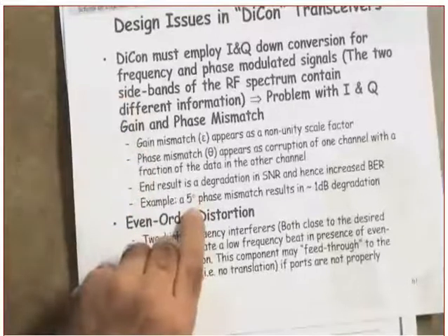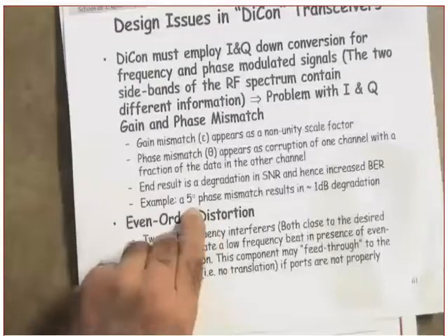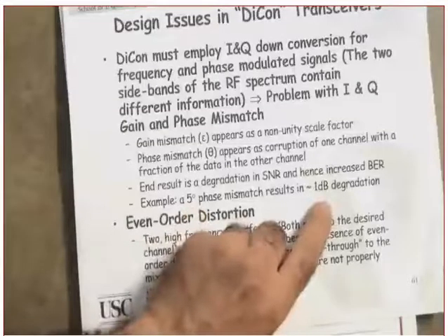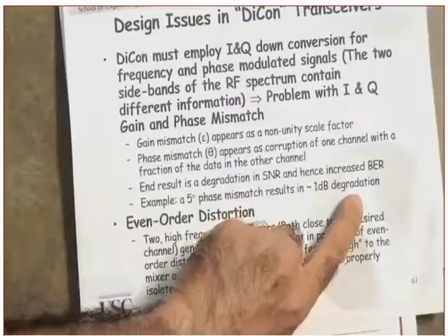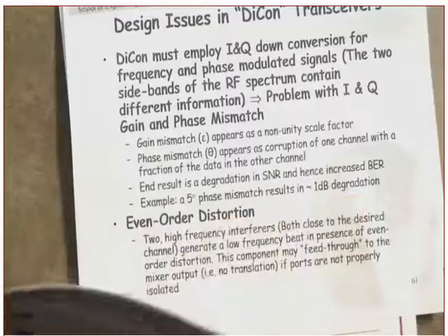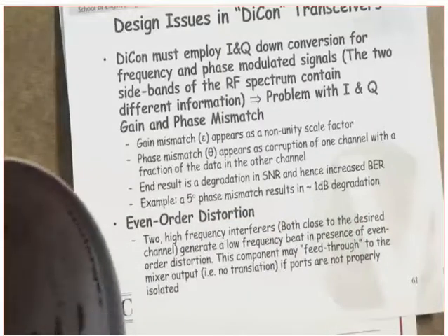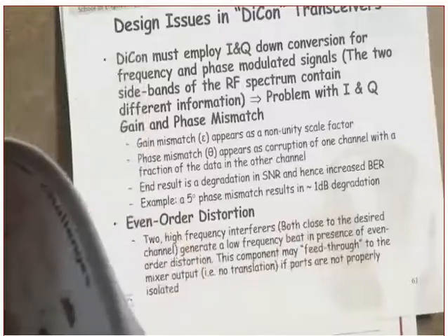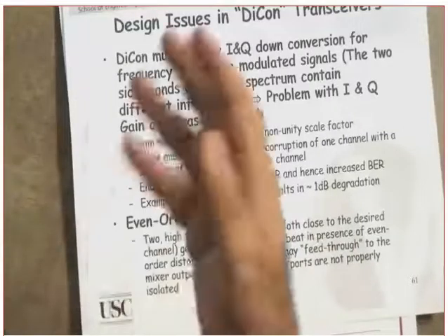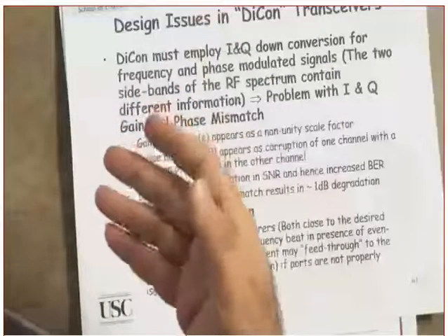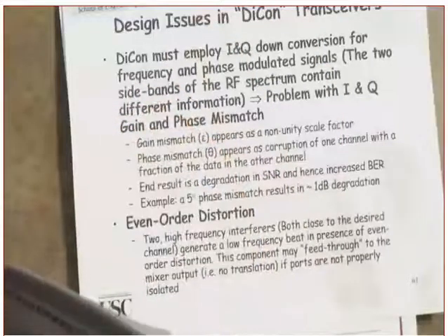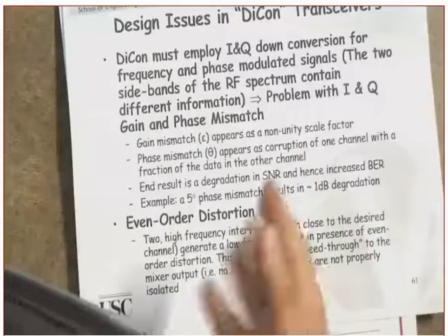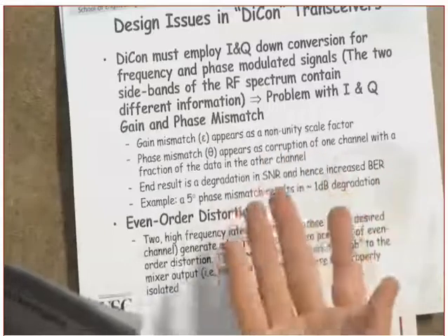That's the opposite of what we talked about. The measurement showed that a 5-degree offset will represent a 1 dB degradation. Are you following or not? 1 dB degradation. Clear? Which means that when we get to the link budget analysis, the following week, we need to introduce in the link budget some degradation losses, 1 dB there, 2 dB there, based on the hardware degradation.